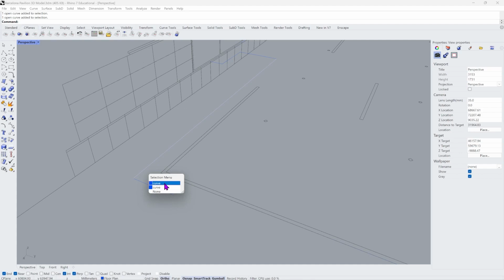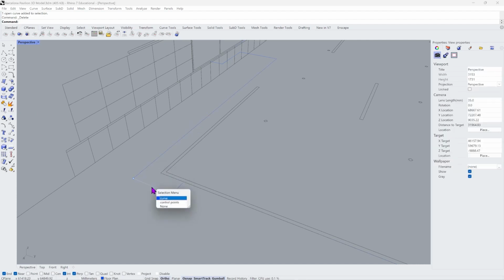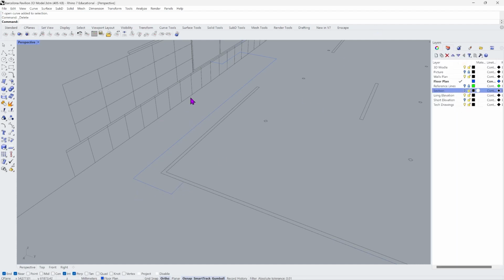So if you do have problems with extrusion, if your solid object becomes see-through, you might want to come back to your original curve, explode it, which is just here, and check every single curve and see if there are any duplicates going on. And when you have deleted all the duplicates, you can just select all curves that you want to join up.